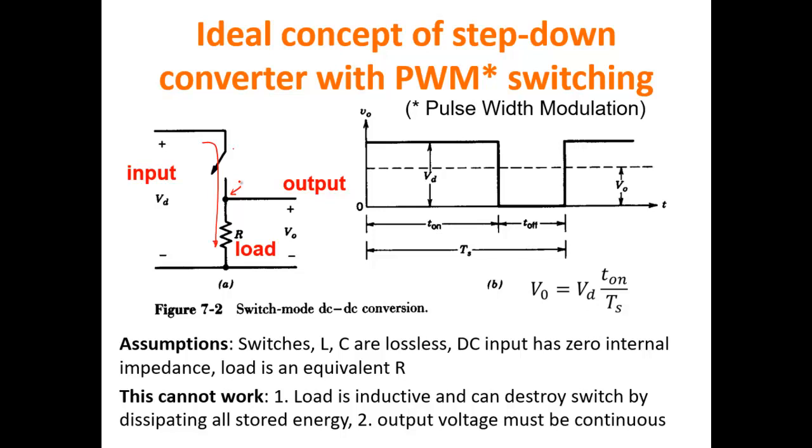You need to always consider that if you want to rapidly change the voltage at the ends of a load that has an inductive component, you typically end up with very high or low voltages on the nodes of the inductor that can damage the circuit. So this has to be taken into account, and it requires some modification.